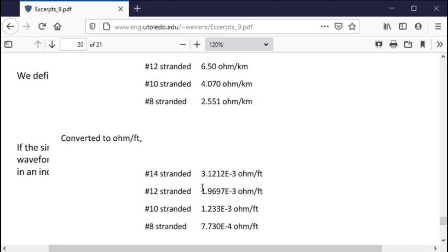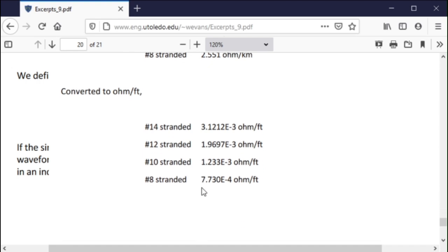That's something that's done quite a lot. People have what we call a rule of thumb, where they would say, okay, if you go more than, for instance, 200 feet out for a solenoid, typically you would have to go from a size 14 to a size 12 AWG wire in order to make sure that the solenoid would turn on and pull in appropriately. So again, that's just a rule of thumb, but it's a good one, and you can use those rules of thumb to help you, or you can actually do the calculations and see if it's going to suffice.